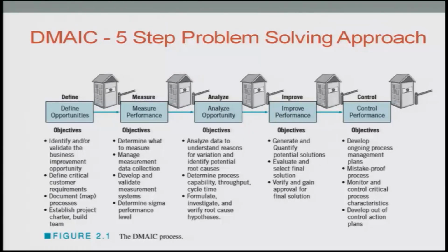So, the problem may be that the coolant which you are trying to use may be bad, or the overall workmanship is bad, or the training of the workman is not good, or the humidity on the shop floor is very high, which has a negative implication for raw materials that may be very sensitive to humidity, or, for example, the temperature may be high, or there may be a lot of dust particles on the shop floor, or it may happen that the raw materials being supplied are not of good